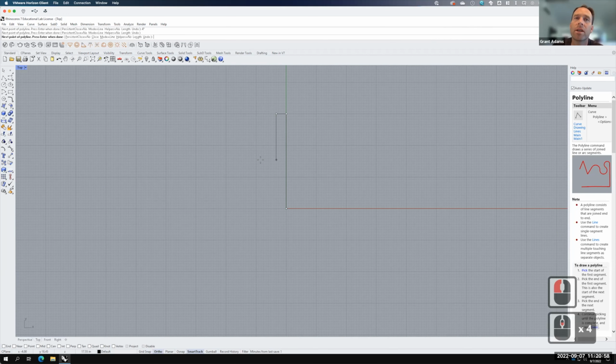So thus far today, we've done the direction and the length. But this next piece, we're actually going down 36, but we're also going over another 2 inches. So this is a perfect opportunity to switch back into those relative coordinates that we used in the second lecture, in lecture 202. So to do that, I'll go ahead and type in at, we're going -2 in the x direction, comma, -36 in the y direction. And you can see that when I do that, I get that diagonal line. I'll press enter on the keyboard and that sloping line.